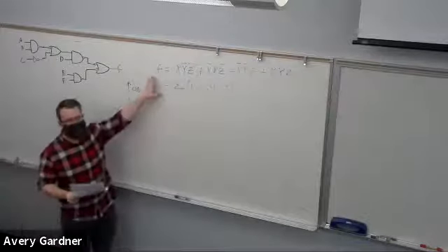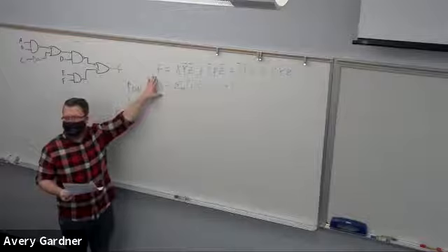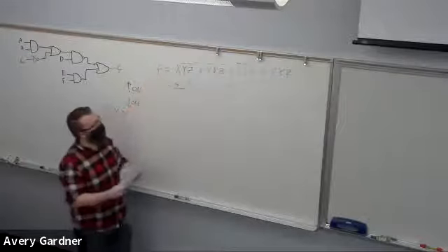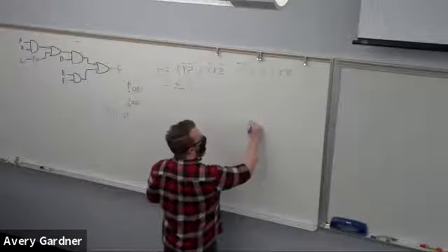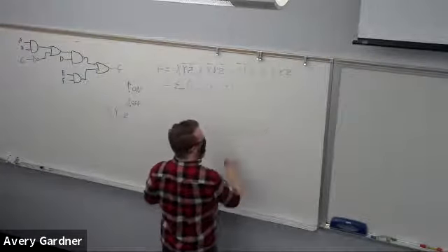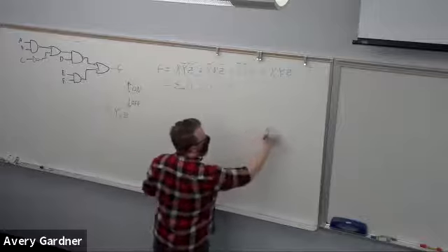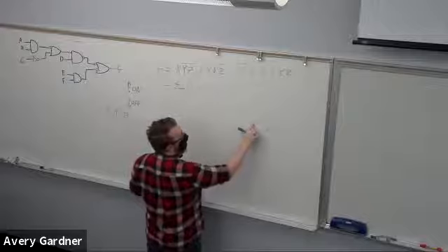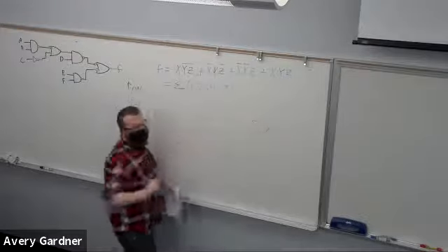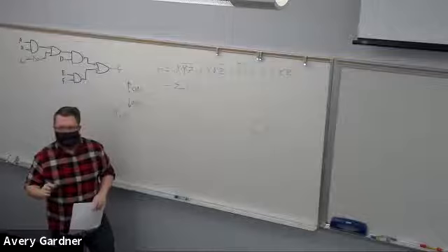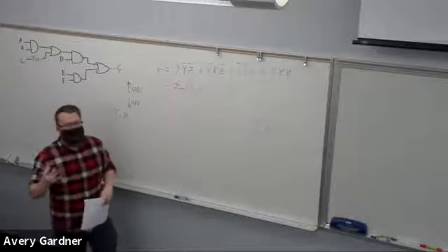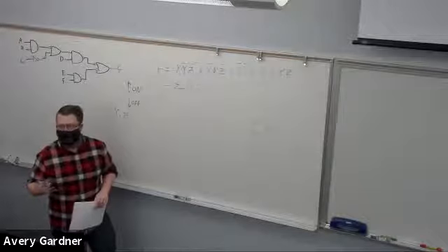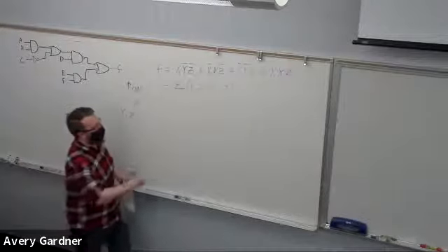It's a sum of products. What is the output gate? An OR gate, yes. How many inputs does this OR gate need? 4 inputs. What is driving each of those 4 inputs? What kind of gate? 3 input AND gates.